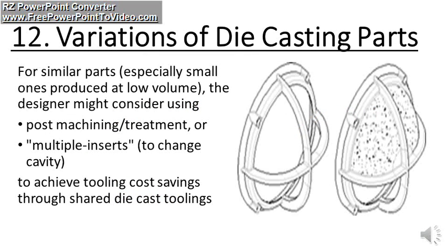12th, variations of die casting parts. For similar parts, especially the ones produced at low volume, the designer might consider post-machining treatment or multiple inserts to change the cavity, to achieve tooling cost savings through shared die cast tooling.